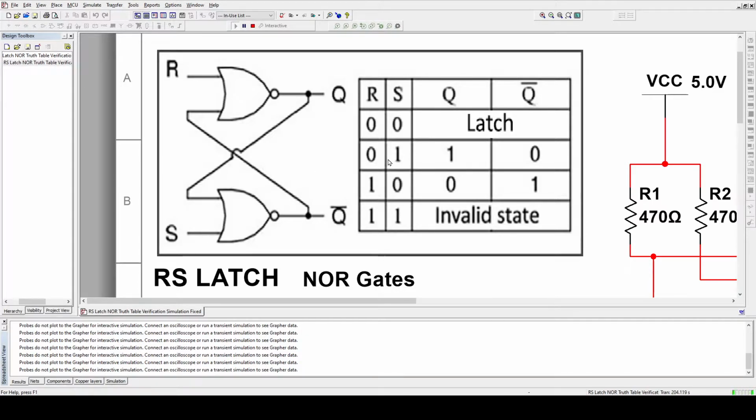Okay. So the latch works on pulses in such a way that, for example, if we apply a pulse, which is a momentary 1 at the S input right here, then the Q output is going to latch. It's going to move into 1.